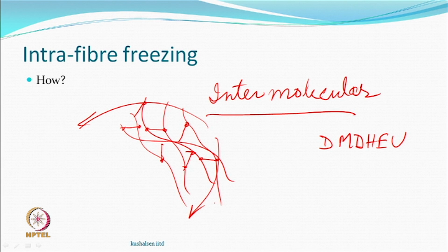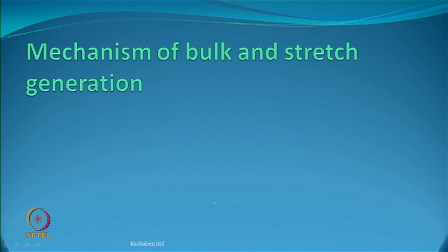So, for texturing, I may say that we may like to have intra-fiber, because each fiber or filament we want to behave individually and not get stuck with each other. A multifilament yarn, all filaments stuck with each other, how will it give me stretch and how will it give me bulk? So, this is what we may probably be requiring.